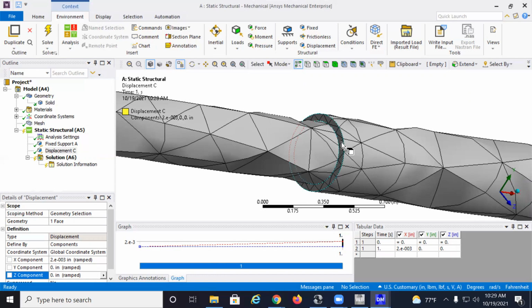On the little ring, yeah, maybe at the most, put a flange or attach a bracket to it and then load it. But you really want the load to be distributed over that surface. Because this is symmetric, the point of action, if you're trying to find an equivalent load, will be going into the center. But there is no way we can go right inside and apply the load in real life.